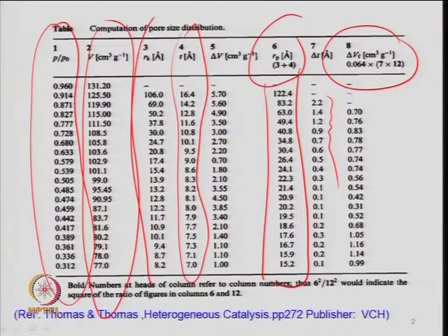Vapor pressure in a small pore is lower, so pore filling is first in the small pore, but when you look at desorption, it is inversely proportional to the radius of the capillary. So, the pressure is released, the pore immediately gets vacated, and that is the region where you get a kind of hysteresis.